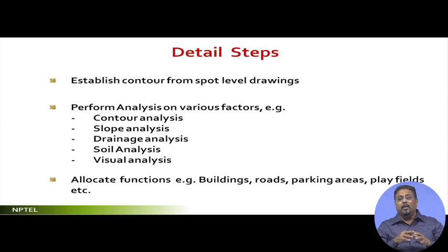See, it is meaningless to go for very minutely measuring all the elevations. It is not necessary. If you find a flat land where a few corner or reference points' elevation will give you a good idea about the topography, that is good enough. But if you find in between there are some bit of changes, which I have explained in my earlier lectures, then you further subdivide and go for detailed elevation recording. So, from there establishing a contour is the first step of the landform work.